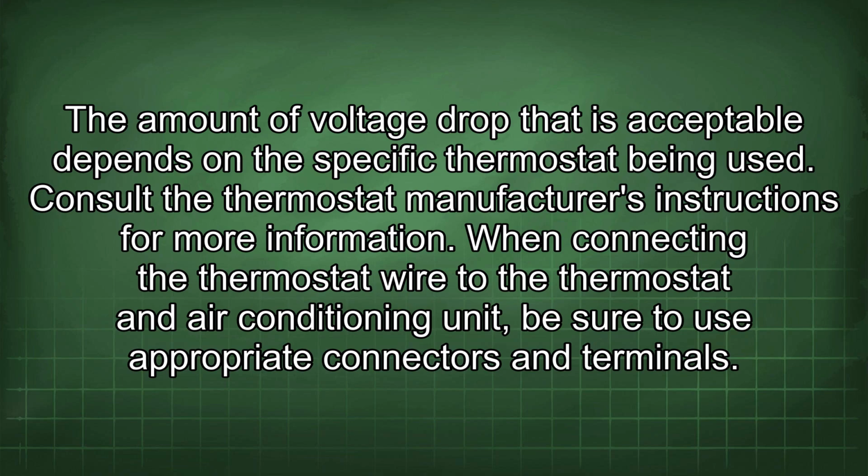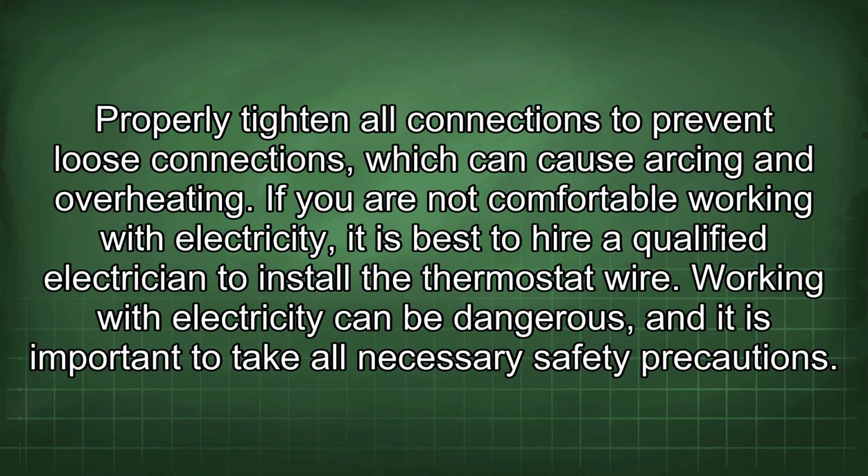When connecting the thermostat wire to the thermostat and air conditioning unit, be sure to use appropriate connectors and terminals. Properly tighten all connections to prevent loose connections, which can cause arcing and overheating. If you are not comfortable working with electricity, it is best to hire a qualified electrician to install the thermostat wire. Working with electricity can be dangerous, and it is important to take all necessary safety precautions.